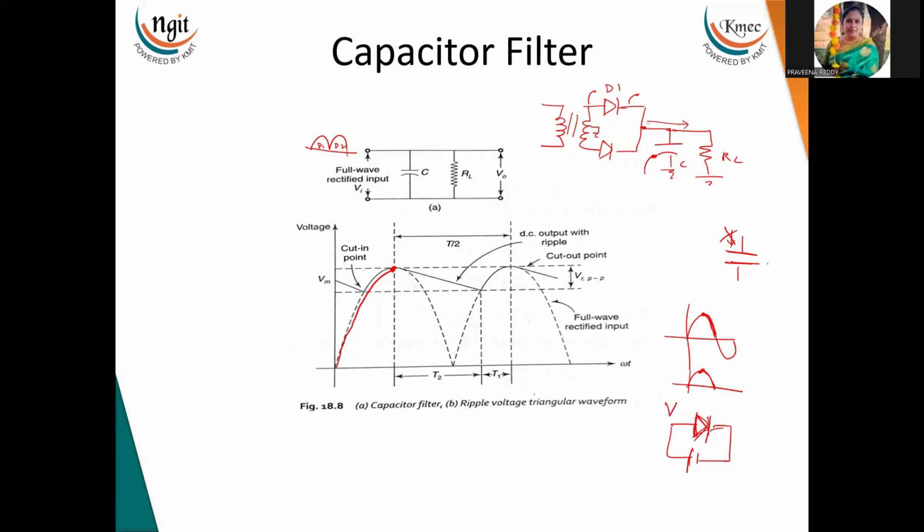Now if I am applying V voltage over here and V voltage is there also, if both the voltages are equal, then the diode will not conduct. If the anode voltage is V plus 0.7, for silicon, then we can say that the diode is in forward bias and it will conduct. Whatever supply you apply, negative or positive, we need to check that the anode voltage is greater than the cathode voltage. Then only can we say that the diode is conducting.